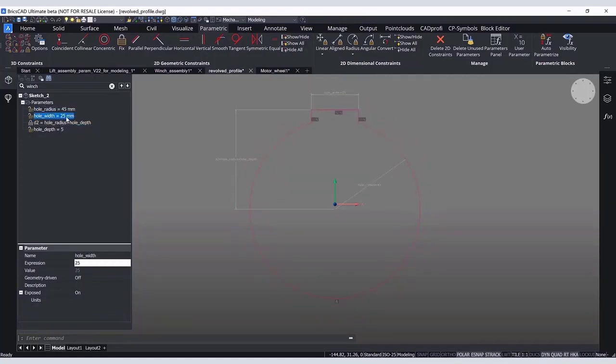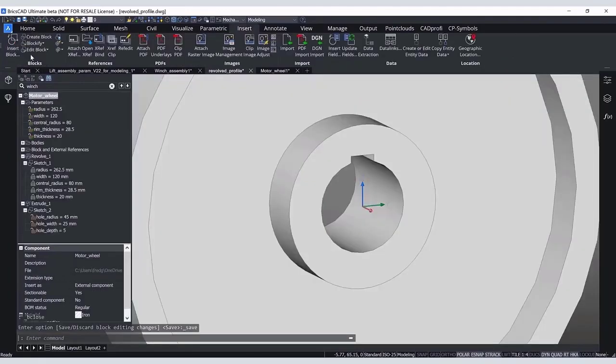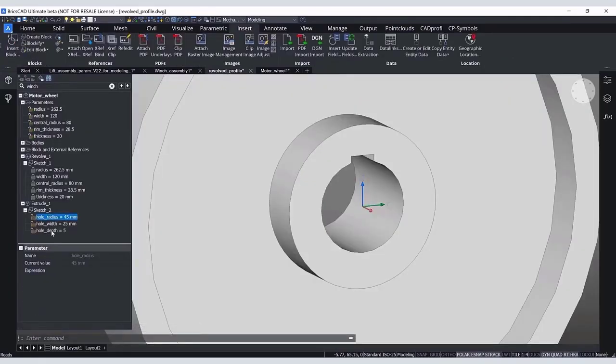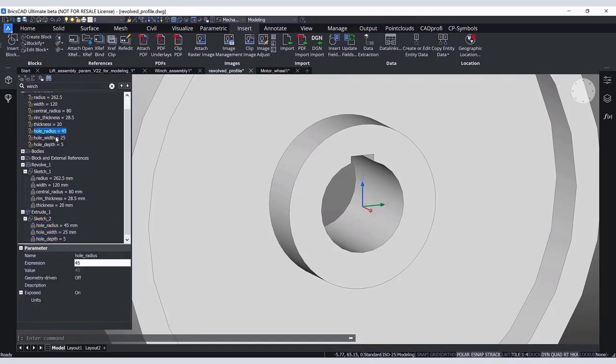We again need fixation, radius of this hole, and width and depth of this protrusion. And again, use animate to ensure that everything was done correctly. Now we almost finished with the wheel. Let's again link hole parameters. Here we will get 3 new parameters: hole radius, hole width, and hole depth. Use animate on them to check that the wheel will be updated correctly.